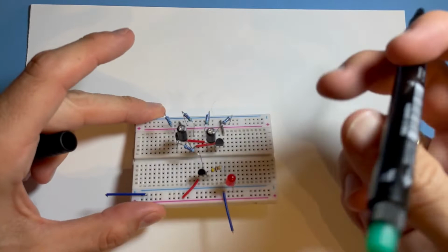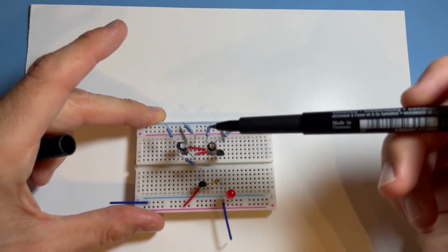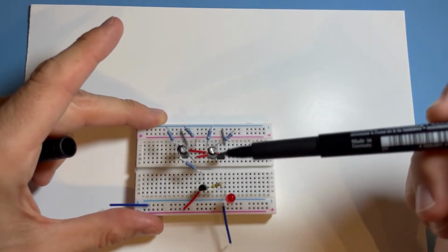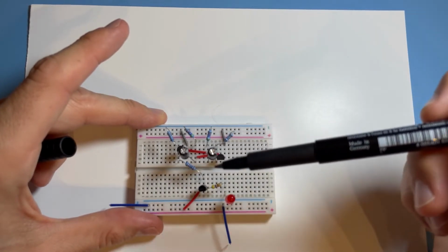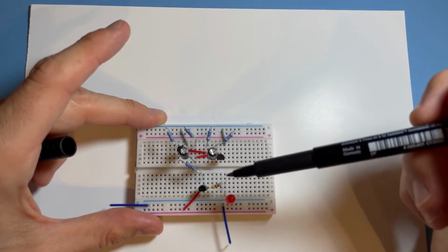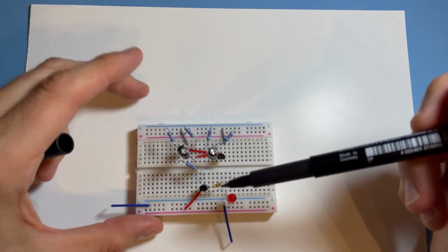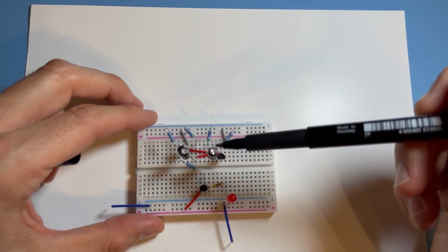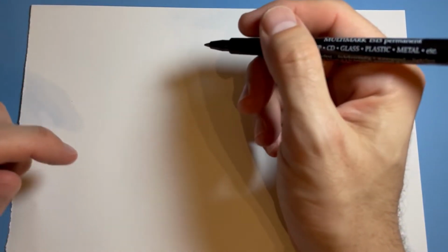So basically it's two capacitors and three transistors and around 5 resistors, and a 6th resistor for the output stage, just to give the LED some front resistor to not put too much current through it. So we'll use 6 resistors, 3 transistors, 2 capacitors. And it's really easy. It looks complicated, but it's really easy once you draw it. And so let's start drawing.